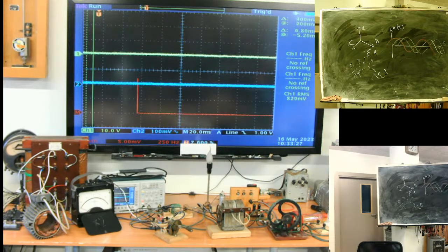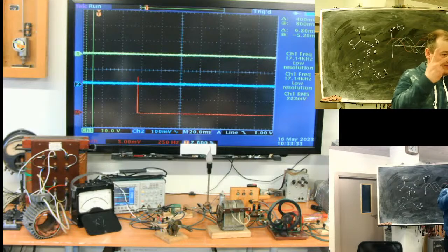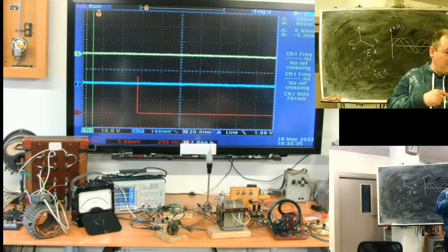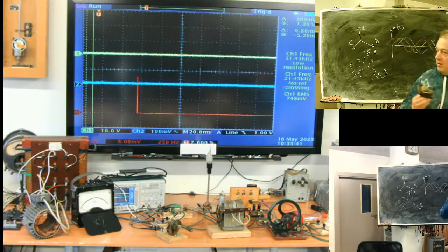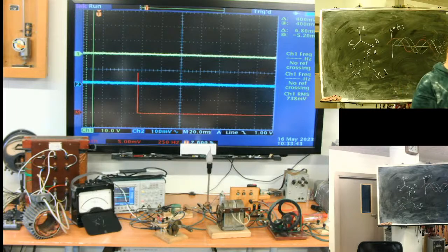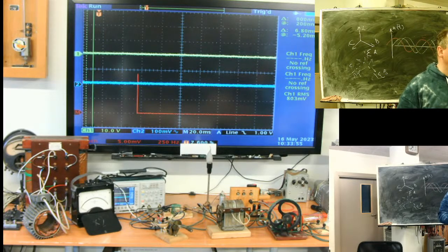What do I have in my hands? A motor. How many phases? 2. It's a 2-phase motor. See? One second. But this kind of motor is not the best one. Why? The magnetic field is of elliptic shape, and an elliptic field means vibration.